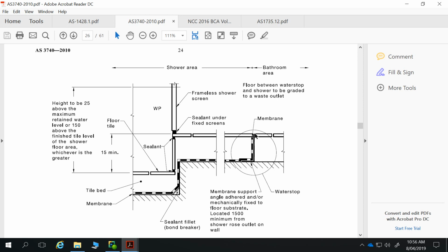You don't want that water stop going past your tiles, because it's a trip hazard, it's unattractive, and it will result in the breakdown of your membrane. But we also don't want that water stop going down beneath our tiles, because that will allow the bleeding and sharing of water between those areas. So you have to include a water stop, and then you paint your waterproofing membrane onto that.